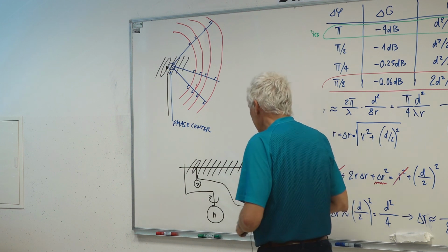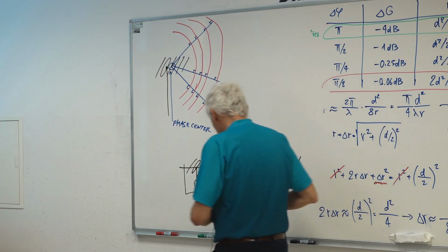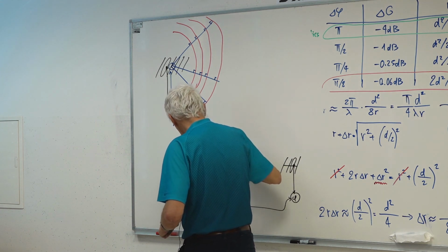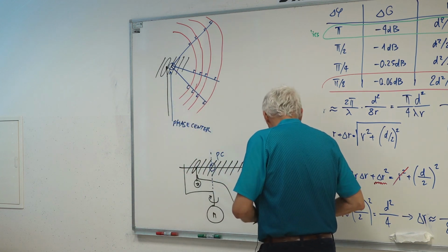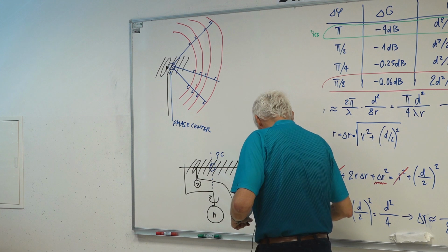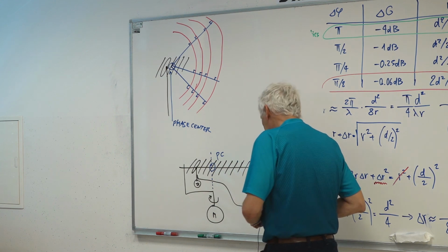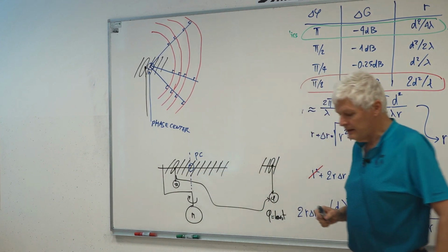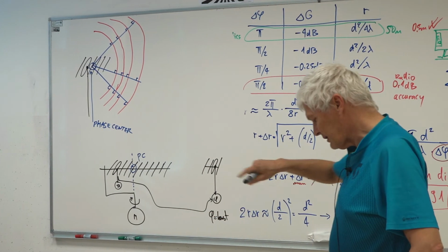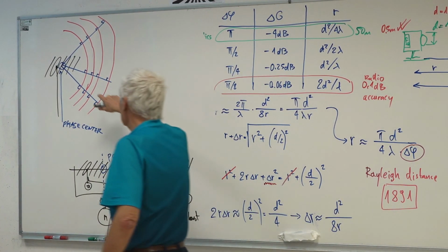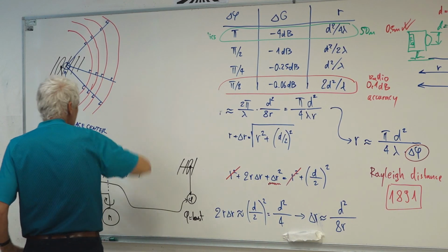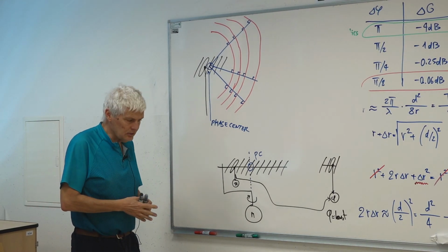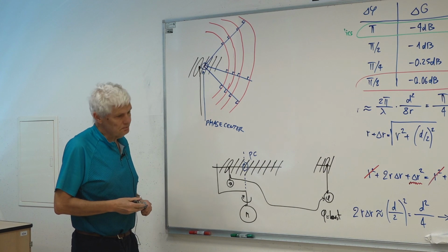And if I'm turning my antenna, if the axis of rotation of my antenna goes through the phase center of this antenna, then this angle phi here is constant. If I miss the phase center, then the angle changes. The phase angle changes as I rotate the antenna, because then I'm not turning the antenna around its phase center, so the phase will be changing. So this is the way to identify the phase center of an antenna you don't know.